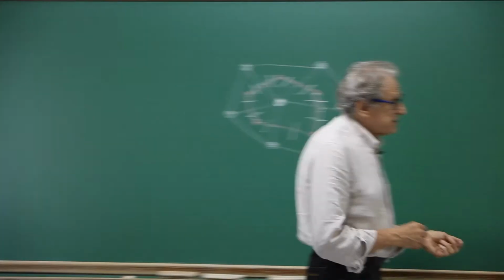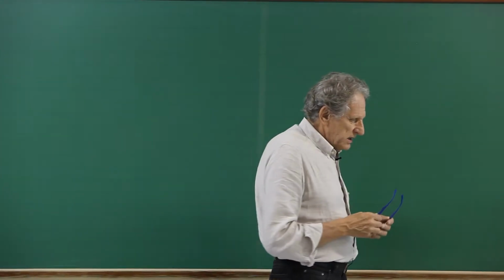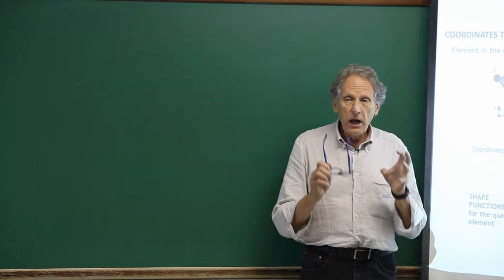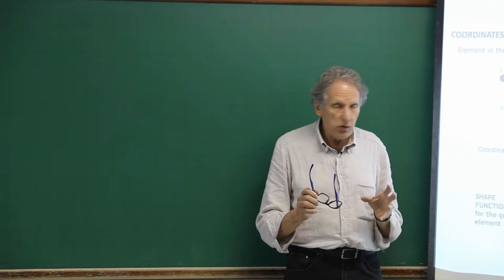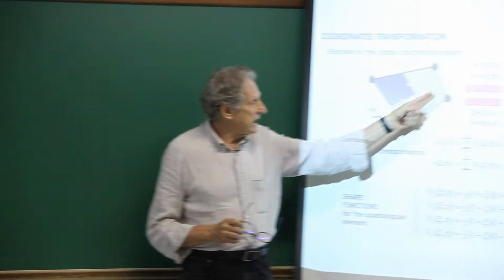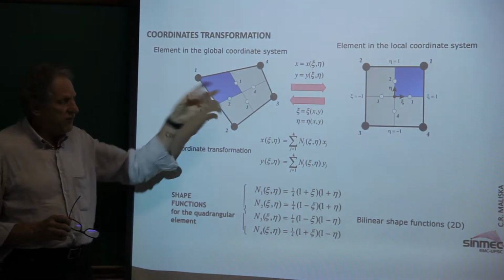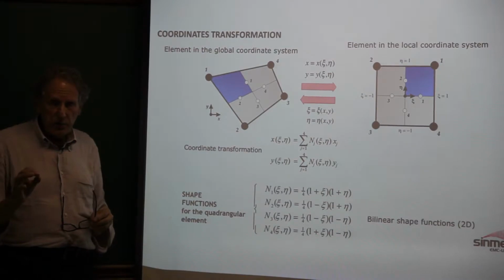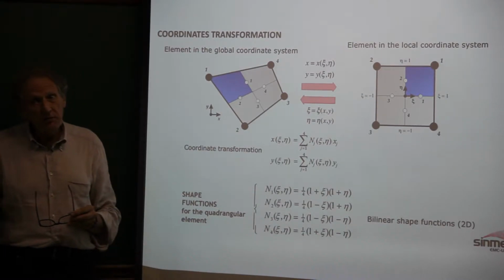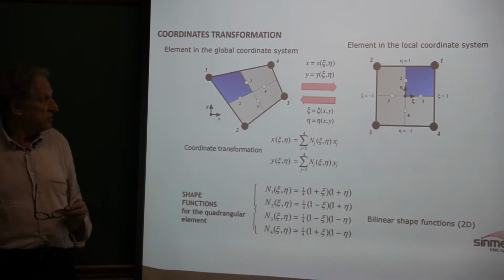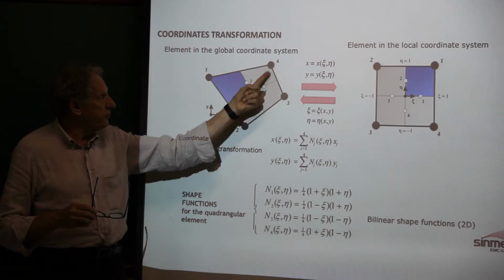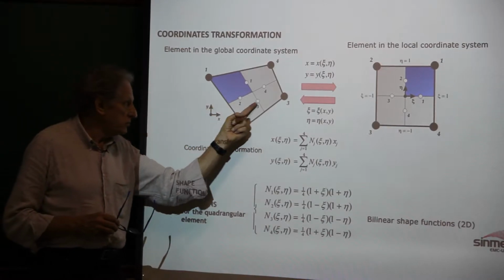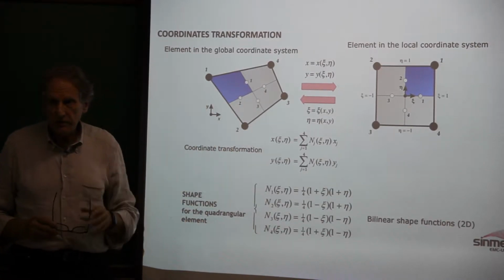What's happening here is the same as we have seen in the curvilinear coordinate system. There is a local transformation now. Imagine you have an element here. Every element has a number of integration points equal to the number of nodes, of course. I have 1, 2, 3, 4 nodes, 1, 2, 3, 4 sub-elements, 1, 2, 3, 4 integration points.